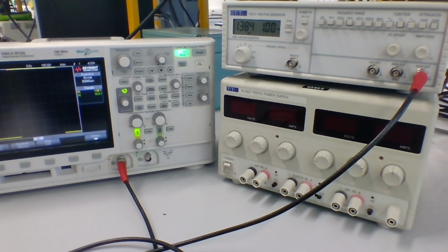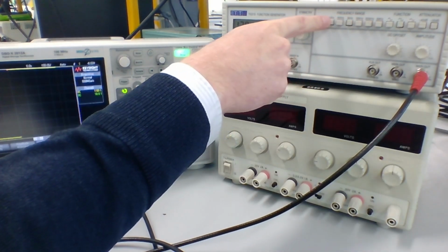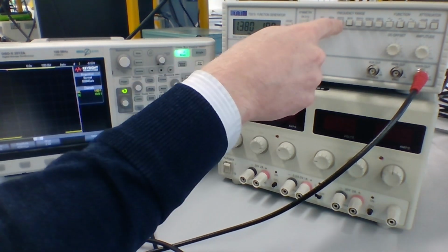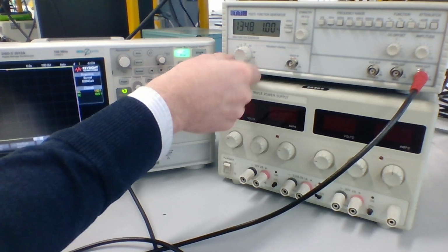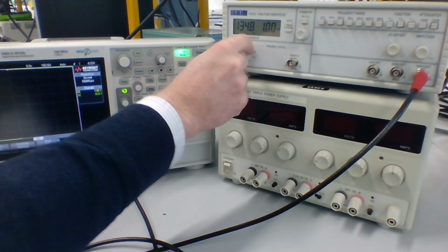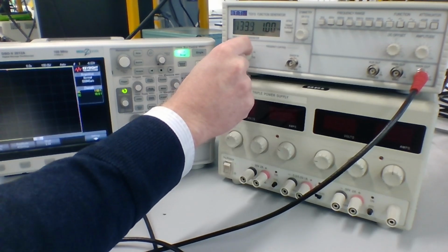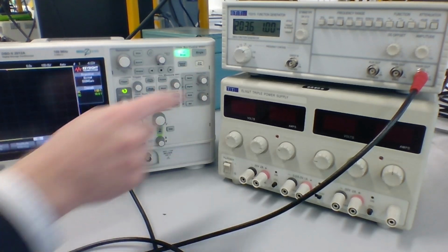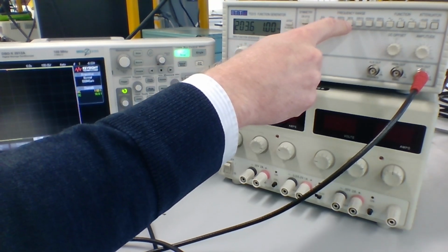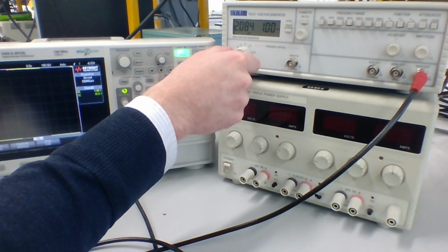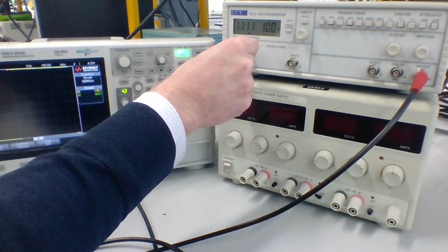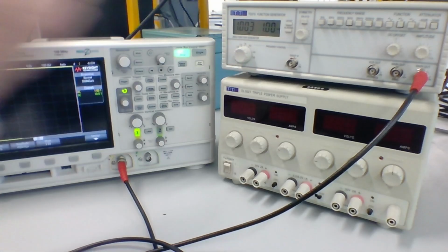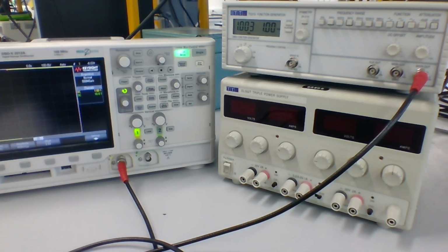We want to set the frequency as well. You see there are a number of buttons up here for frequency range, and these give us the range of frequencies we're operating within. So if we're in the 300 range, we can use this dial to adjust from low tens up to higher hundreds, maybe 300-ish hertz. We want 1 kilohertz, so let's go into the single kilohertz frequency range, the one labeled 3 kilohertz, and set the dial to about 1 kilohertz. There we go. So that's about 1 kilohertz.